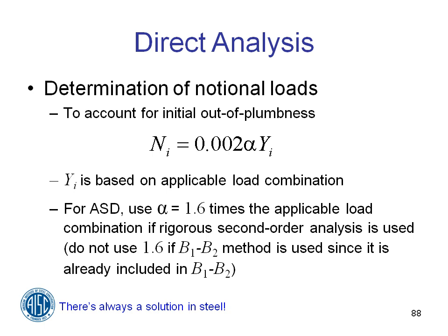That's all right. You had talked about stiffness reduction back on slide 62, and the question was, does this apply when using composite sections? Yes. Yeah, the stiffness reduction applies no matter what your system is. And in fact, if you were combining this somehow with a reinforced concrete wall or something, you'd have to try and figure out how to reduce the stiffness of those other elements. It's not covered in the specification specifically, but anything that is part of your lateral load resisting system, the stiffness has to be reduced.